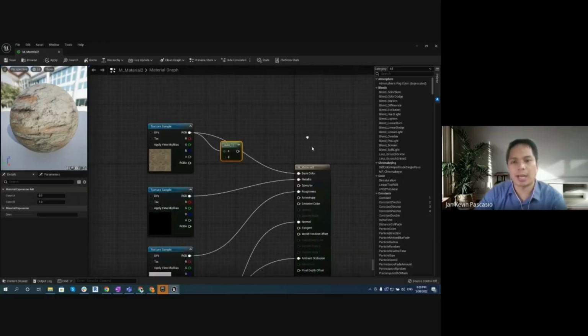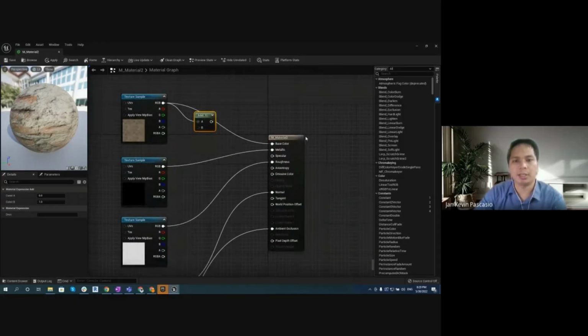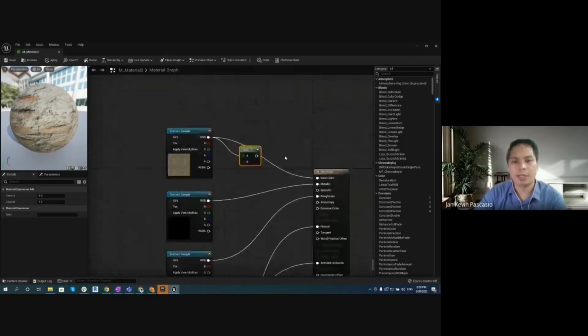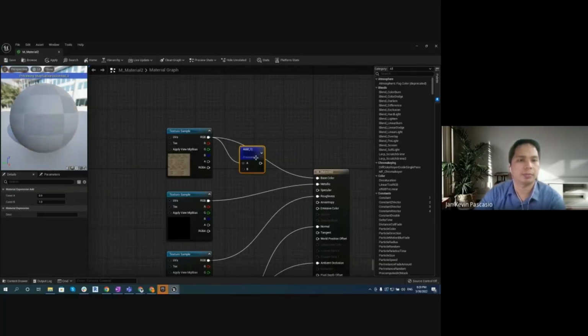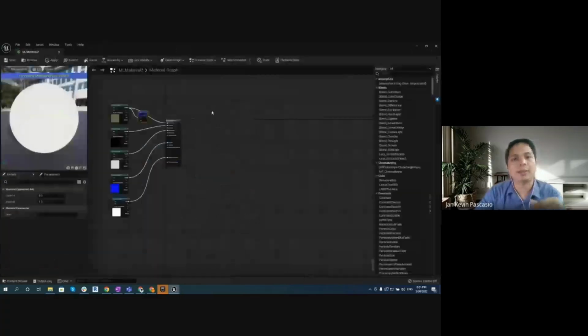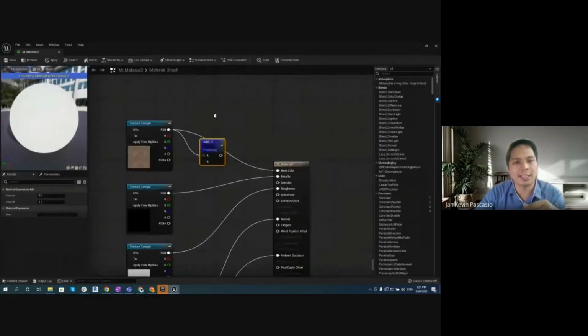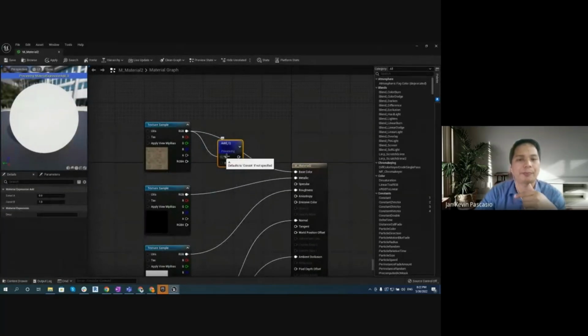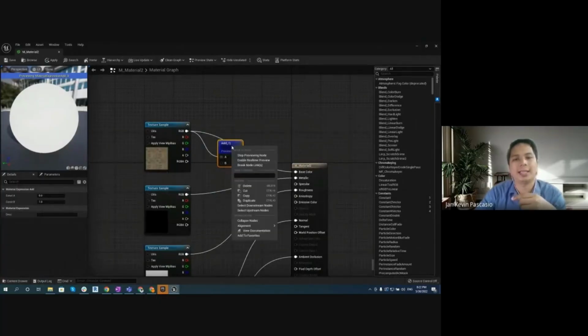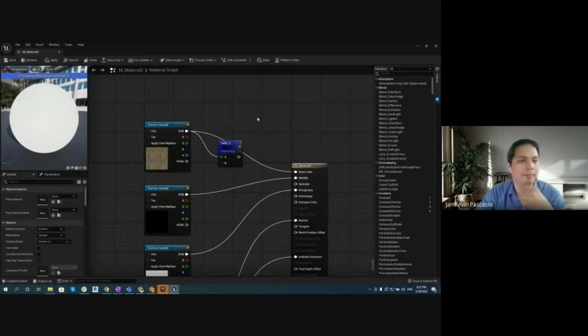It's because this other node is still showing. So what if we want to show whatever is in this node? You just right click on it and then start previewing node. So again, you have connected the RGB to the A, and then right click on the add, and then click start previewing node.